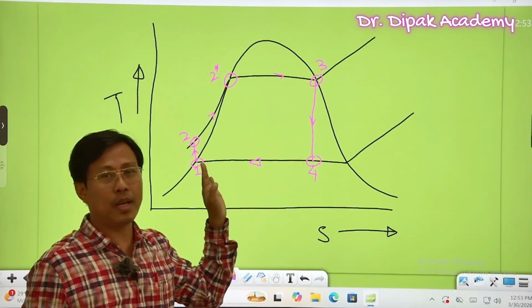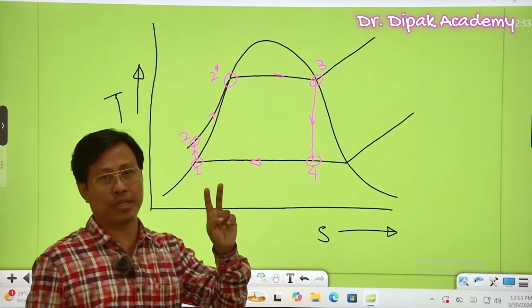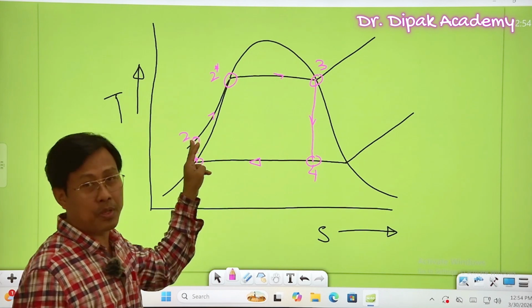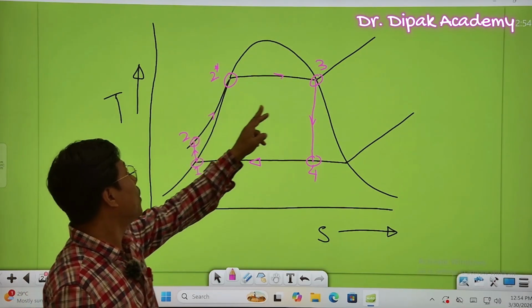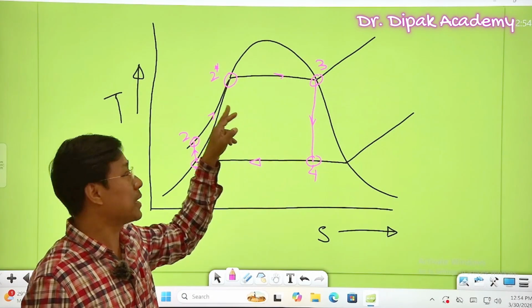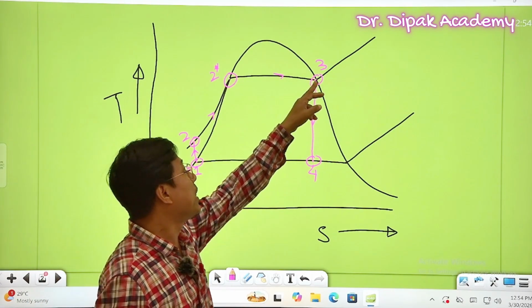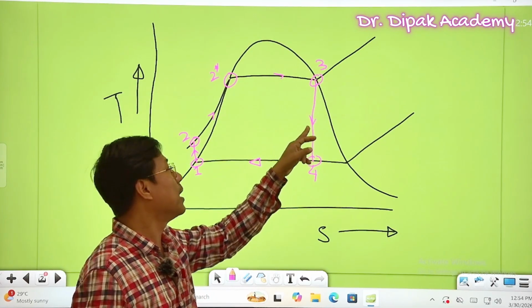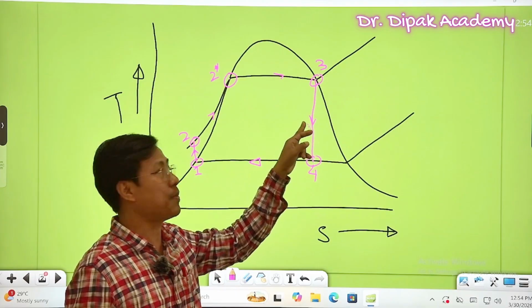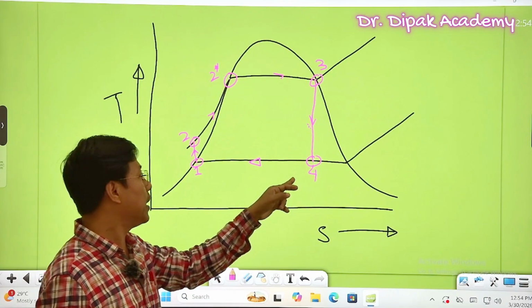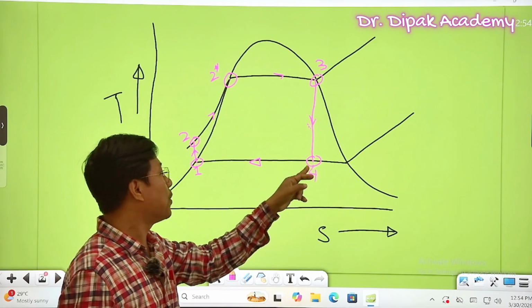So simply we are getting four main processes in this Rankine cycle. First one is 1-2, which is the pumping process, and from 2 star to 3, this is the boiling process which is taking place in the boiler. Then the steam will come inside the turbine where the reversible adiabatic expansion will take place in 3-4, and finally the steam will come to the condenser.